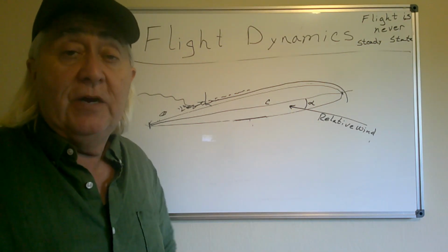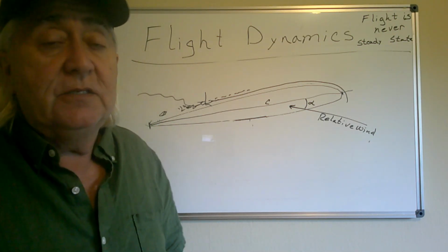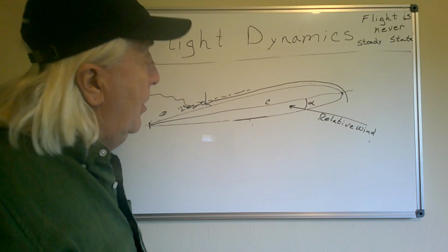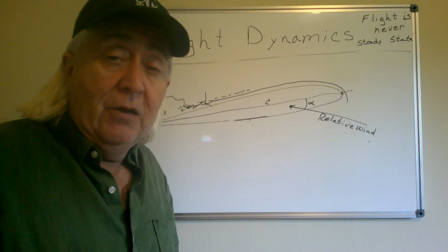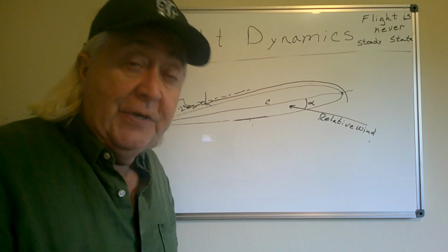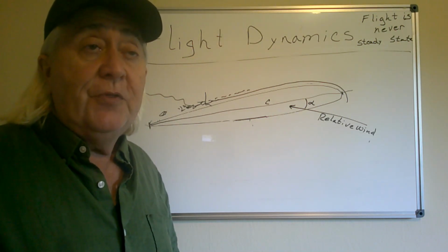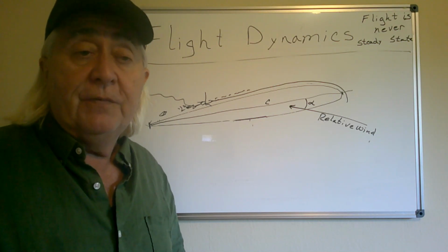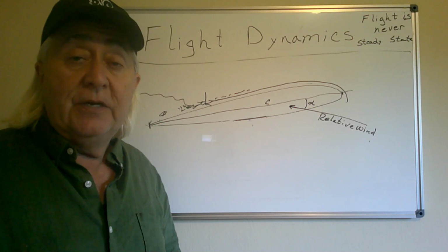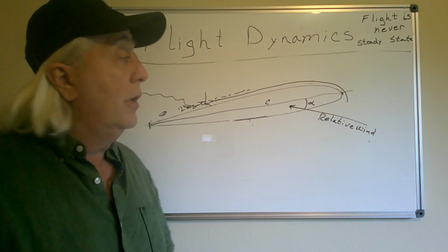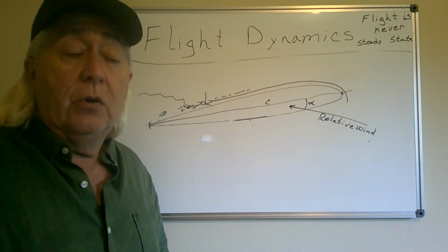So, really important, relative wind is what we really need to know. Where is it? What's our angle of attack? And in that diagram, they don't tell us. But knowing that there was a sharp nose down and a perpendicular descent to the ground tells us a lot. That tells me that something took all the lift away from that aircraft rapidly, much like doing an accelerated stall in a glider, where the flow separates, you lose all your lift, and down you go.